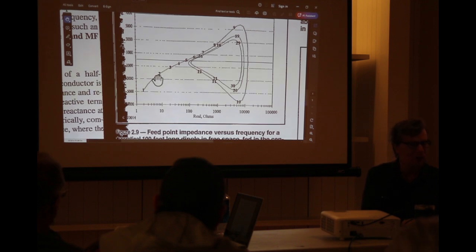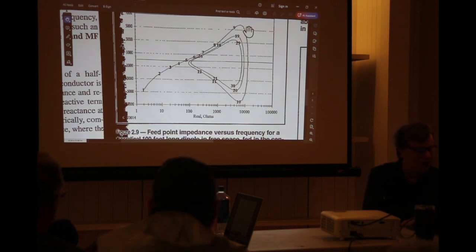Now, what do we know something about here? This is kind of a gradual increase as we go through our series resonance. What do we have here? We have this absolutely precipitous change of reactance from a very high value between 9 megahertz, 5,000 ohms of inductive reactance, to about 5,000 ohms capacitive reactance over a very small frequency range, okay? This is our anti-resonance point. These are what you want to avoid, like the Ebola virus, if you want to make an antenna that's broadbanded, okay? So yeah, there's a very dramatic change of reactance.